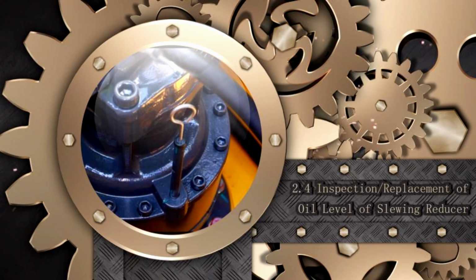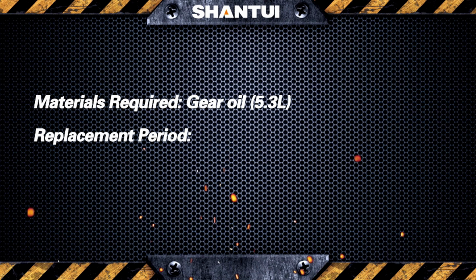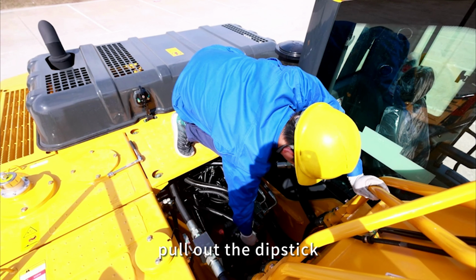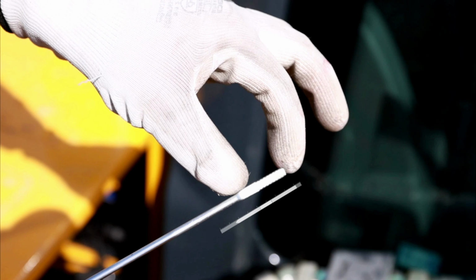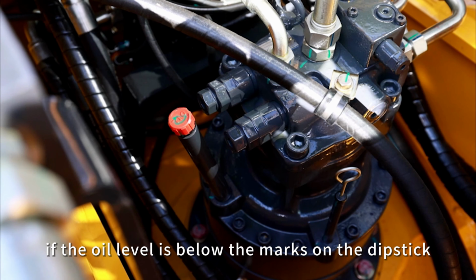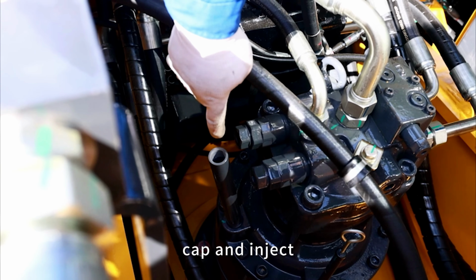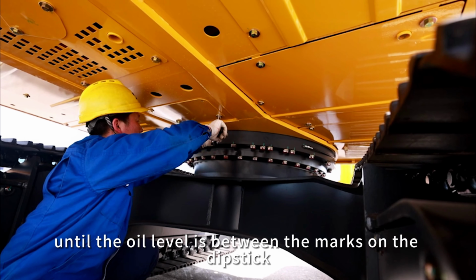Inspection/replacement of oil level of slewing reducer. Materials required: gear oil, 5.3L. Replacement period: replace at 500 H of initial use, and then replace every 1,000 H. Steps: pull out the dipstick and inspect if the oil level is between the marks on the dipstick. If the oil level is below the marks on the dipstick, remove the oil injection cap and inject gear oil until the oil level is between the marks on the dipstick.